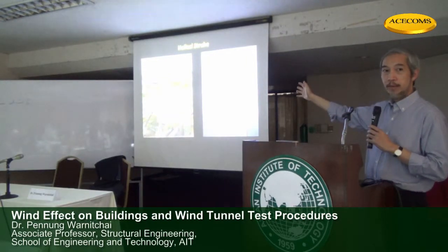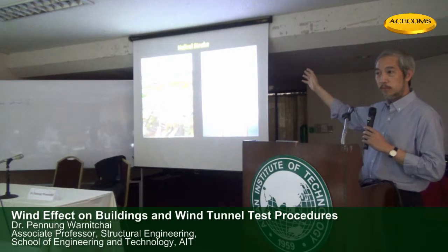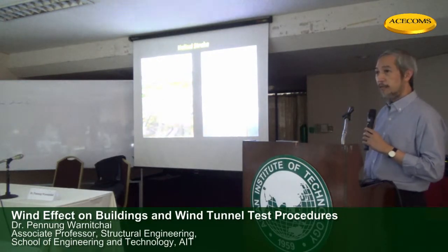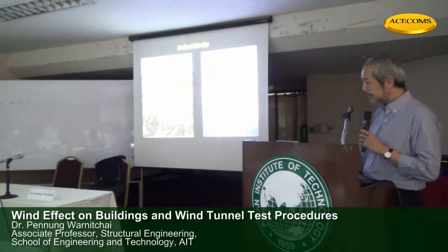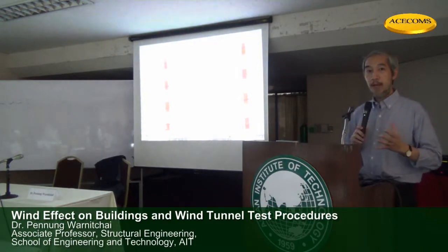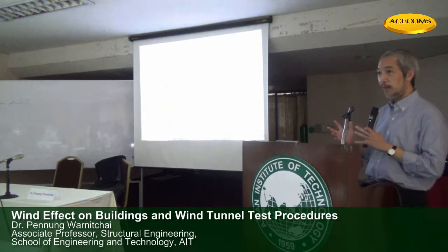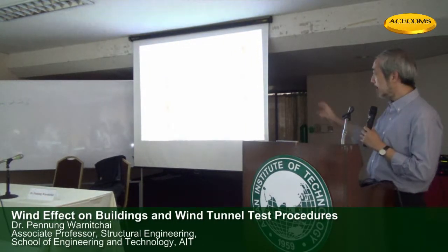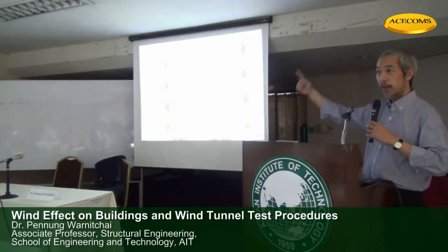This idea works very well in a small model in the lab. But when we try it in the actual prototype, I got a very conflicting report. So we are actually not sure that this approach will work, but it's widely used. This is another approach. If you have a very slender stack and you want to prevent the vibration or the wind effect, you have to have an external skeleton. Or if you have space, you can put a guide rope.